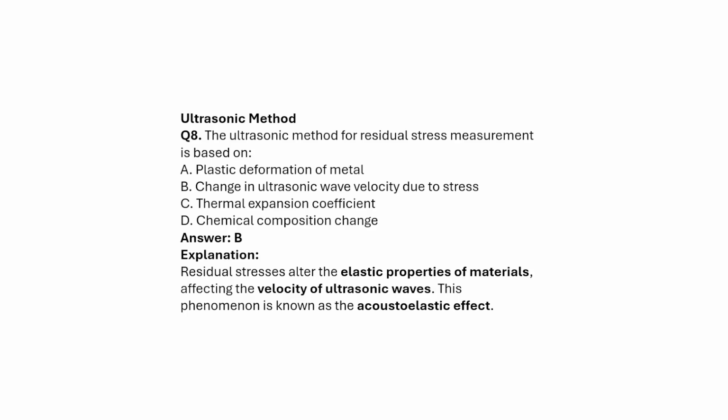The ultrasonic method for residual stress measurement is based on the change in the ultrasonic wave velocity due to the stress, rather than plastic deformation, thermal effects, thermal expansion coefficient, or chemical composition change.